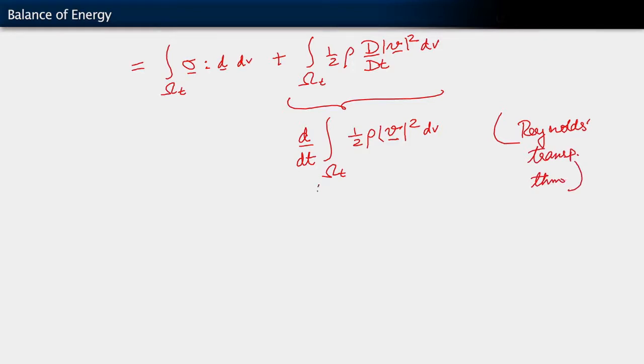But then this quantity is what? We recognize rho dV as being an elemental mass, and the magnitude of its velocity squared multiplied by dm, and 1/2 of that gives us the kinetic energy of each elemental mass. Integrated over the volume, it gives us the total kinetic energy.